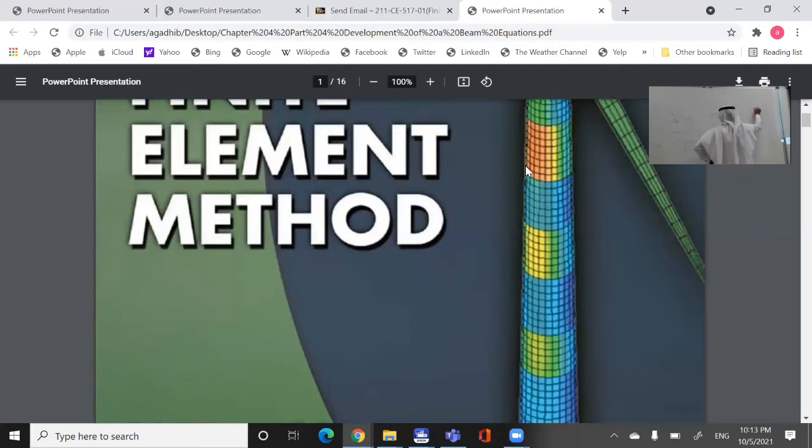I know this. M over EI is the second derivative of the deflection. Is that right? Yeah. Okay, what about the shear? There? Yeah. So this is V over EI, like that? Yeah. Okay, so once you know V, you can find the strain.